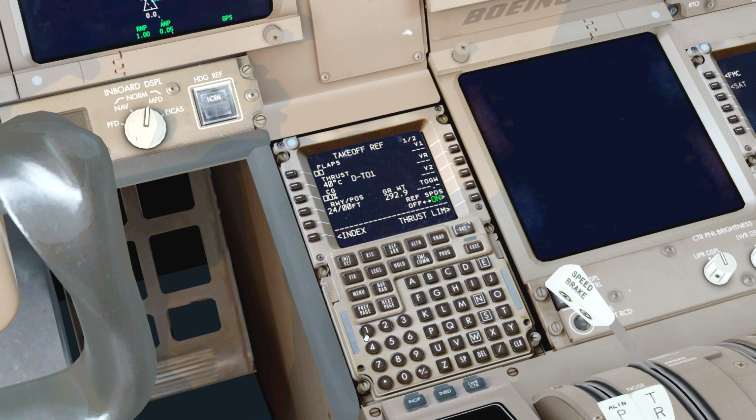Now with the takeoff page, depending on the airline, you may use different flap settings. Again, also on the performance calculation, you may get a different flap setting. I'm just going to take off with flaps 15 in this case. Center of gravity, basically that is determined by the aircraft itself, in the simulated aircraft that is. So you can just click this line select key and it will come up with the center of gravity value itself.